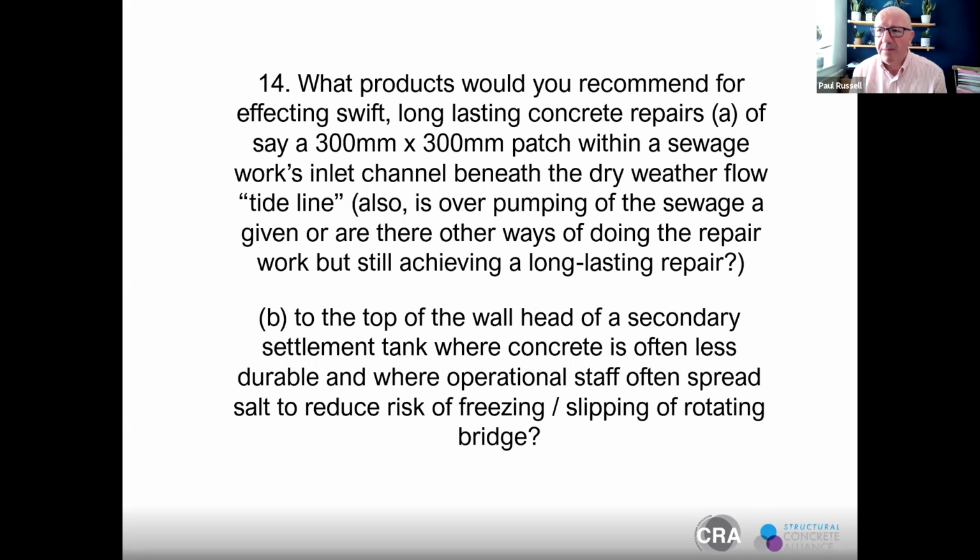Feather edging I wouldn't recommend because of the type of traffic that's going onto it. And then using a repair material that is compatible with the existing parent concrete. I recommend epoxy mortars quite a bit in that sort of scenario, because you don't have to take away so much concrete. You can keep it quite small in dimension. So epoxies are very good at repairing edges of nosings to expansion joints and floors, definitely.